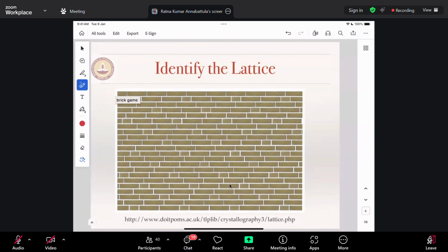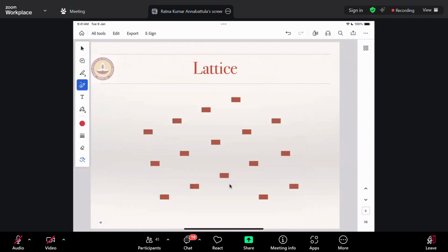For the structure, we are trying to identify a lattice. So we have identified one reference point and all the similar, equivalent, exactly same kind of reference points in the structure. Now you remove the structure and these are our points. And this is what we call a lattice. In this fashion, if you keep repeating, then you will form the lattice in 2D. So this is the lattice that describes the structure that we have just now erased. But is this the unique lattice for this particular structure?